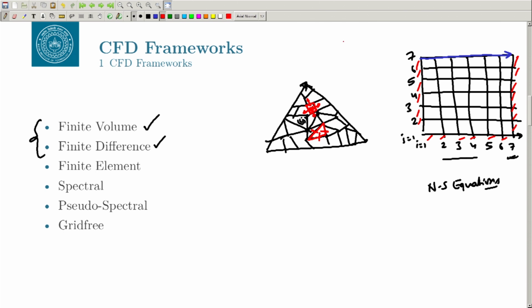So, for every edge, okay, where the flux may be going, you know what is the left cell, what is the right cell, and this is my edge of the cell, right. So, in this case we solve an integral form of the Navier-Stokes equations instead of doing this del u by del t plus c del u by del x equal to 0. Okay.